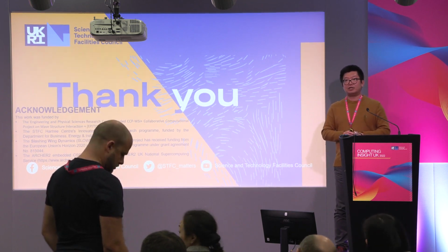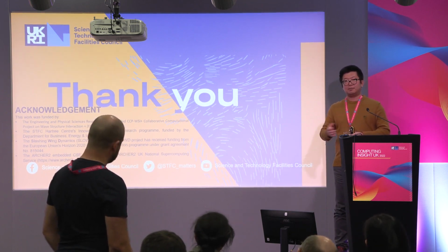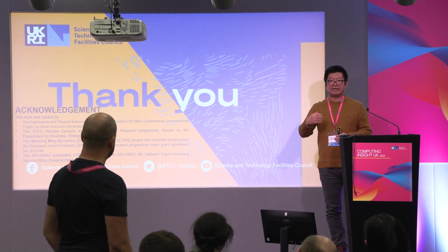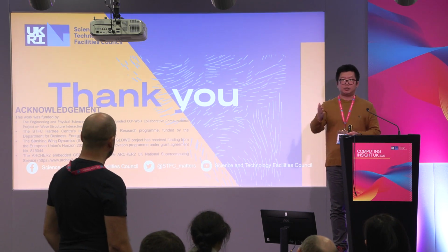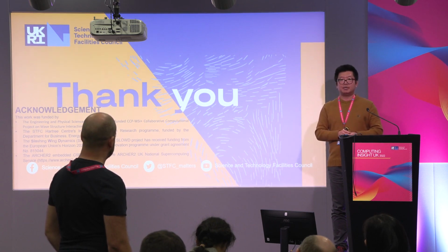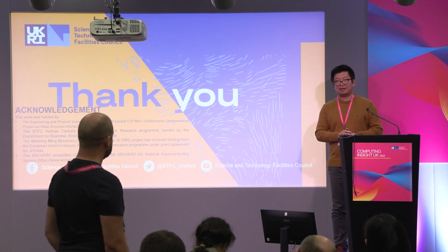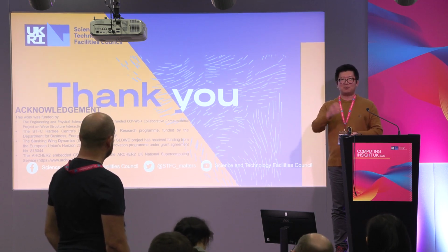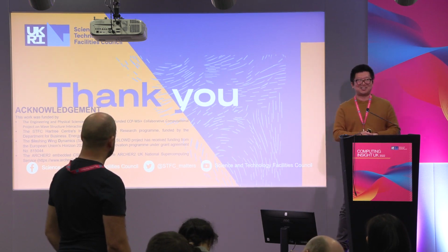Yes. And Omar has led research looking at different turbulence models inside OpenFOAM. According to his research, we picked k-omega SST for that sloshing case. But it's ongoing work, and we have found some very interesting things inside the turbulence model, and maybe Omar will present in the next time.